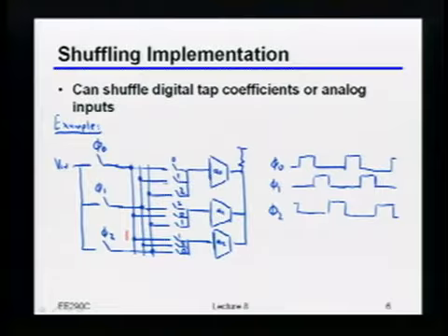And just to be clear here, I've sort of drawn what the clocks tend to look like. It doesn't necessarily have to be this way, but usually you do build them as these non-overlapping clocks. So in other words, each one of these clocks would be 1 bit time wide in our particular context. Okay? By the way, that also has an implication on how you'd build the circuitry that generates these things. Because that implies that you need some counter running at the full bit rate, and then a whole bunch of comparators to figure out when this particular clock phase is supposed to be high.